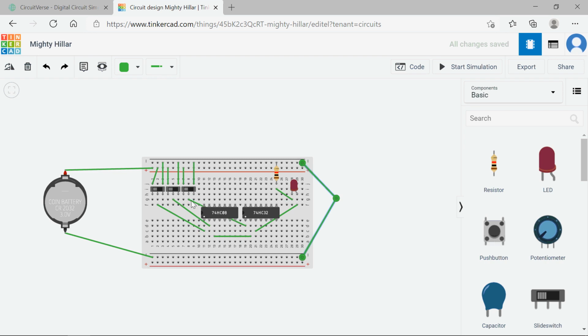Okay, do I have everything connected? So my inputs here, the way the switch works, when the switch is on the left, it's going to connect this pin to this pin, and when the switch goes to the right, it's going to connect the middle pin to that pin. So they're called terminal 1, common, and terminal 2.